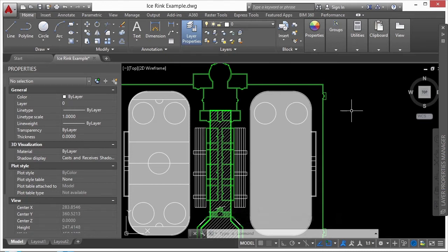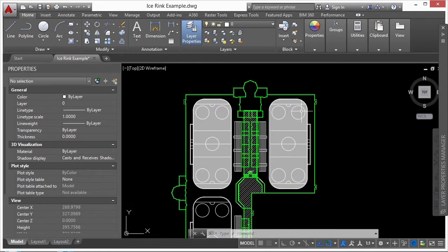Now, another similar command is called hatch to back. You just type that in, hatch to back, press enter, and it moves all hatch patterns in your file to the back. Hatch to back, text to front are two commands you're going to want to run often, just to make sure, because a lot of times the hatch just somehow moves up to the front and it's blocking out everything so you can't see it.